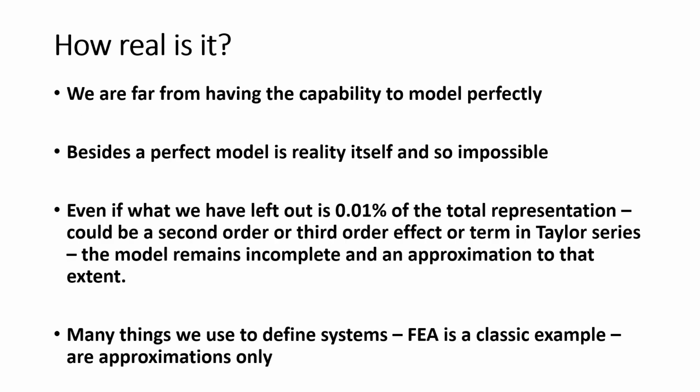How real is such a model? We talked about modeling a motorcycle using a very simple point mass, a stiffness, and a loss model. Well, it is quite real, because it's possible for you to predict the response to a situation using a model which, if the weight and the stiffness and the damping are taken accurately, will probably be 85 to 90% accurate. Once you find it's 85 to 90% accurate, you start adding finer aspects to it, and the systems become more and more accurate. You may get even up to 95, 96%. Very hard to get higher than that because you start approaching reality.